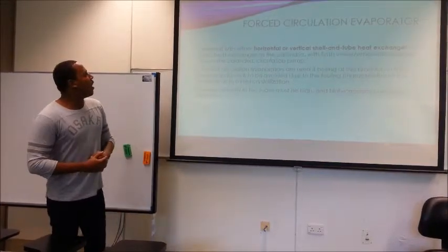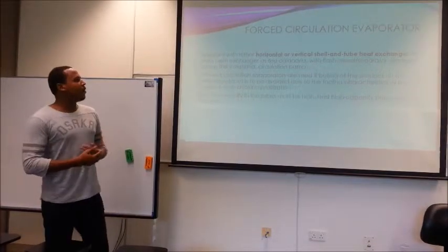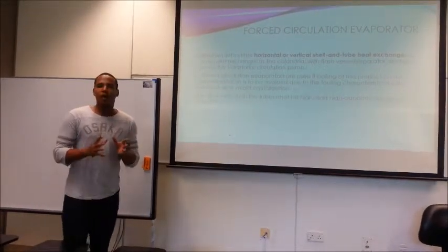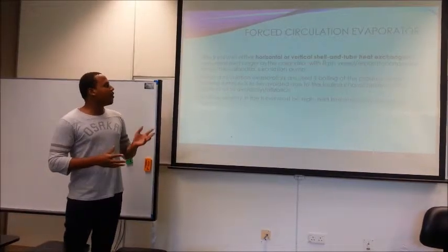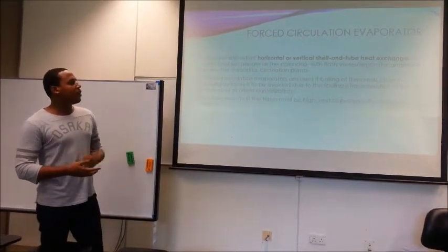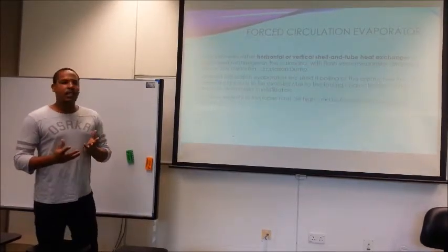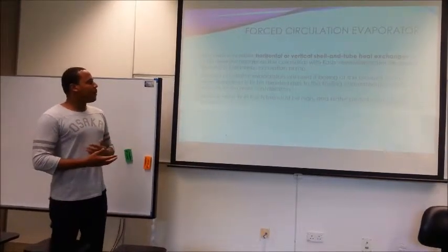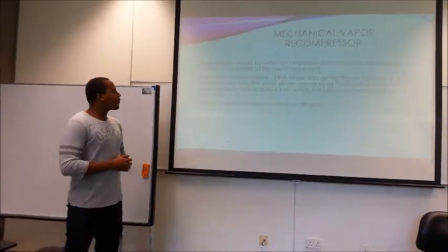Next, please. The forced circulation evaporator. Forced circulation evaporators are used if boiling of the product on the heating surface is to be avoided due to the following characteristic of the product. The flow velocity in the tubes must be high, and high capacity pumps are required.